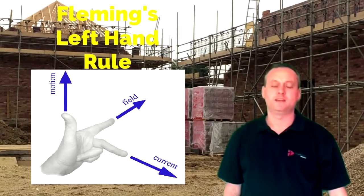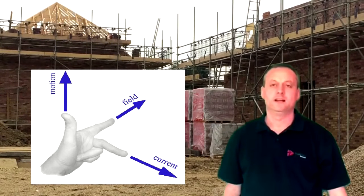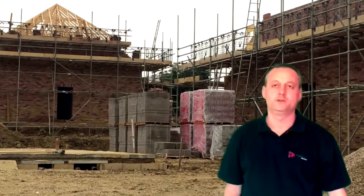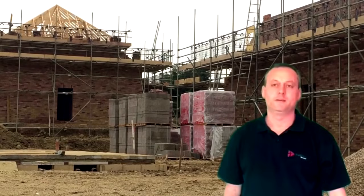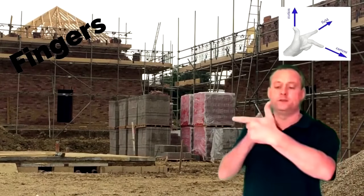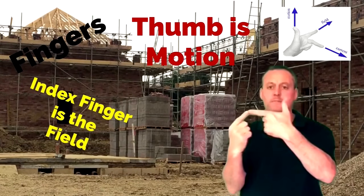And by using Fleming's left-hand rule, you can work out whether the conductor's being thrown up and out of the magnetic field or down and out of the magnetic field. Again, questions in our exam like to use Fleming's left-hand rule. In recent history, they've told you which hand to use when showing you a current carrying conductor placed in a magnetic field, being Fleming's left-hand rule. On Fleming's left-hand rule, it's also worth remembering what each of the fingers is named or doing. So in other words, the thumb is the direction. The index finger from knuckle north to south is obviously the magnetic field.